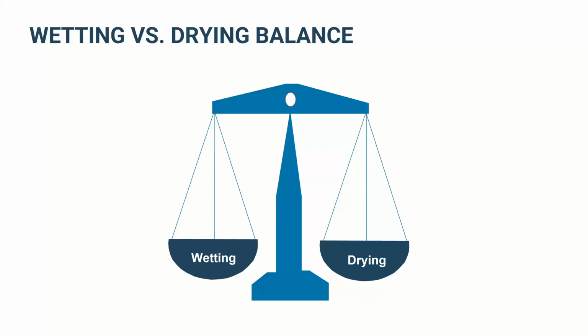All right. So buildings are always going to get wet. We can't control the weather. It's going to rain, and so we need to allow things to dry out and drain. Right. So a well-designed building enclosure has to allow water to drain out and to dry. Some materials are obviously going to be more sensitive to that than others, and that needs to be considered in our design.